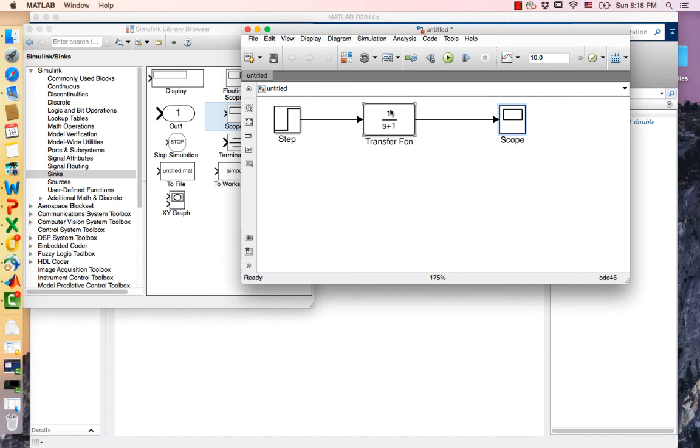As you can see, this is more or less our first order system. If you remember, the first order system has static sensitivity, or static gain, of 1, and time constant 1, because tau s plus 1 is our first order system. If I have a step input, then through this transfer function I will get a plot that gradually increases and gets to steady state.